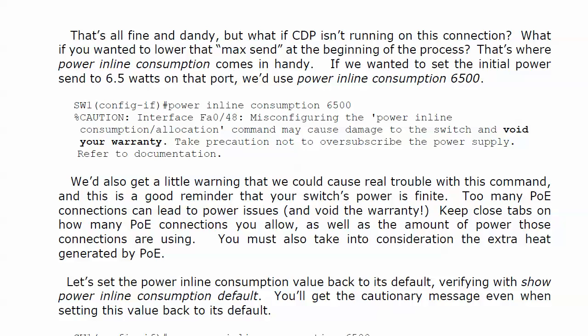And actually, if you go out to Cisco's website, they have some great PoE documentation out there. It's very well written, very understandable. It's so good you'd think I wrote it. And he said modestly. But the thing is, if you pull the PoE documentation for a certain switch model, Cisco's going to tell you point blank at the top, hey, you really need to go look at this other PDF we have on installing PoE, and make sure that you've got enough cooling in your server room for the amount of PoE that you run.